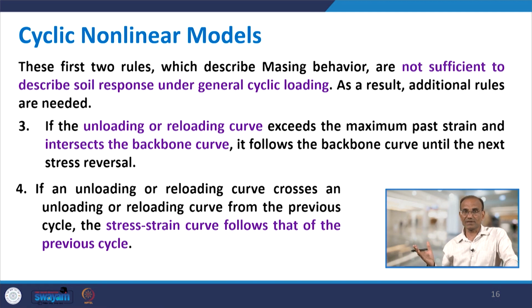Unloading or reloading is almost like unloading, but there is a difference. You load and unload. After unloading, if you reload again, that will be called reloading. So, if the unloading or reloading curve exceeds the value of maximum past strain that was intersected, then it will follow the backbone curve up to the next stress reversal.